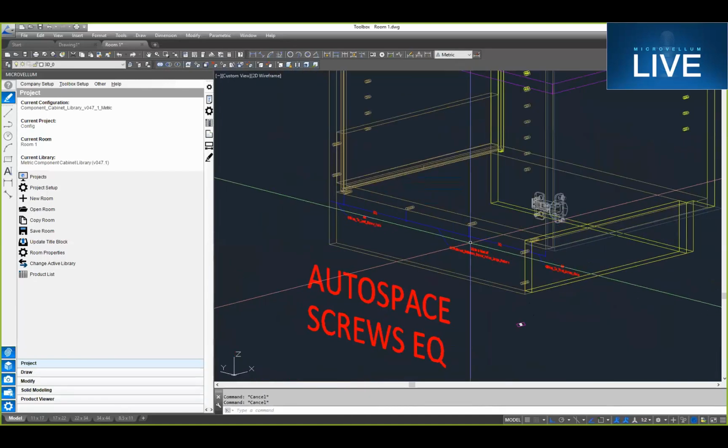That works really well if you're just using screws to construct the cabinets, or if you're doing something like a Dado construction and maybe you don't have a case clamp to put those products in, so you're clamping them up by hand. You want to just throw in some screws to hold those things together while the glue sets so you can get them back out of the clamps. Adding those screws in is a quick and easy way to do that.